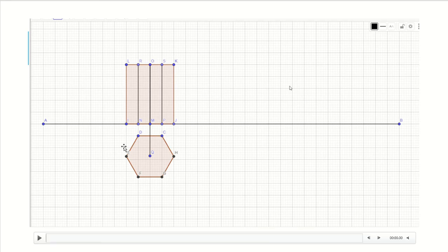So see this. This is how the top view looks. This is how the front view looks. After which, what you need to do is draw the lateral development. Draw the development of this. Okay, lateral development. That means it is having six sides. What is the length? It is 25 mm. So go for 25 into 6 is 150. So go for 150 mm length line. Divide that equally into 6 parts. Fine. Thus you create the development.